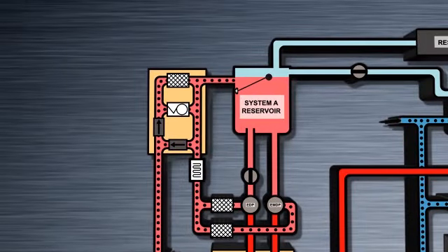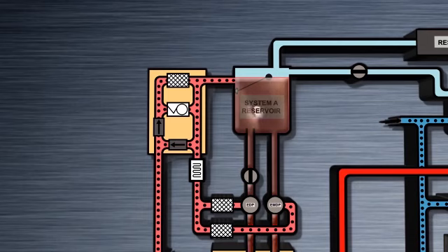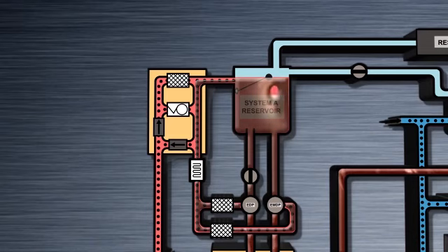Each pump has 2 outputs, an output pressure line and a case drain line. The output pressure line does as the name suggests. It pressurizes and provides fluid to the rest of the hydraulic system. The case drain line drains a smaller quantity of hydraulic fluid away to be filtered and cooled. It is this case drain fluid that passes through the heat exchangers in the 2 main fuel tanks. Heat flows from hot to cold, so the heat exchanger transfers heat from the hot hydraulic fluid to the cold fuel in the tank. The fluid is then routed back into the reservoirs.